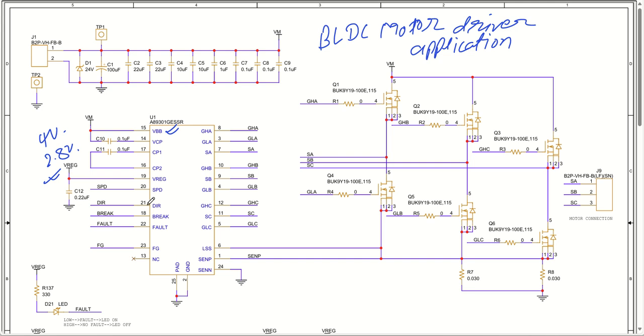So it is a very low cost design. The maximum current that you can draw is 10 milliamperes, so you have to make sure your current consumption from this voltage regulator is less than 10 milliamps. My microcontroller will be taking less than that. We have a power supply connector here. We will need one VM supply, let us say 12 volt or even 24 volt. This particular IC is capable of taking up to 50 volts input, but our design is let us say 12 volt, 15 volt or even 24 volt.